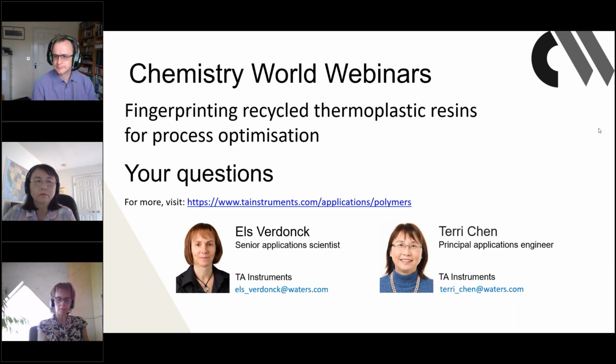Yeah. So Bettina, what you are referring to is also fitting some kinetic models to your TGA data, so you can study the decomposition at different heating rates. And obviously, you are going to see that if you are working at different heating rates, the decomposition will shift to higher temperature with higher heating rate, and from that you can obtain kinetic information. And once you have that kinetic information, you can then make a prediction of how long it would take for your sample to start decomposing at a certain temperature.